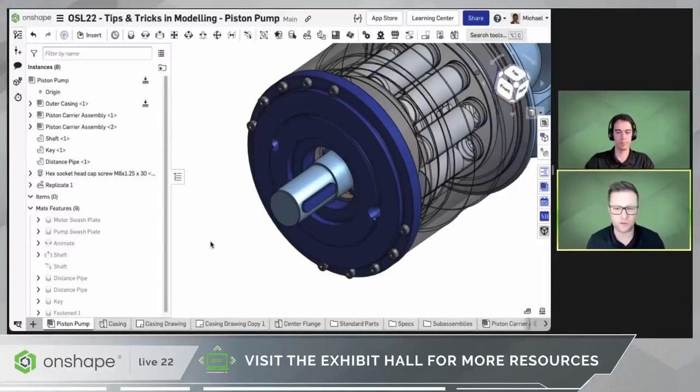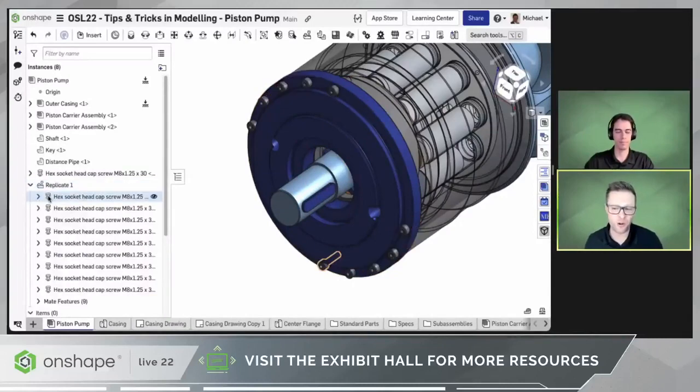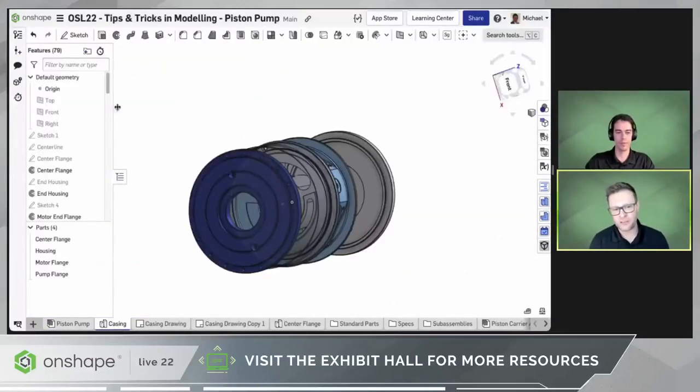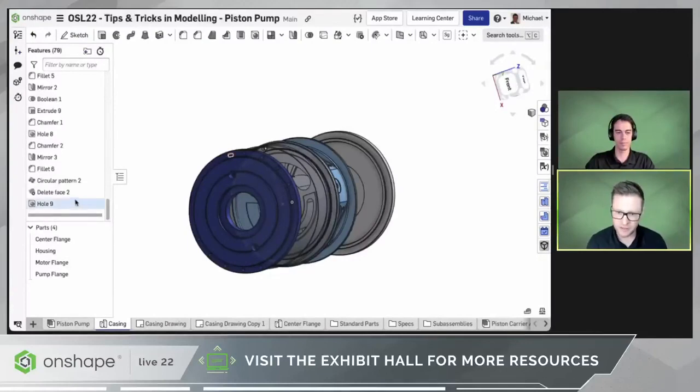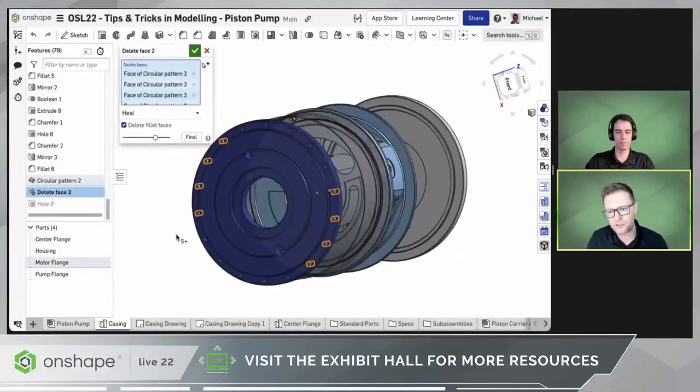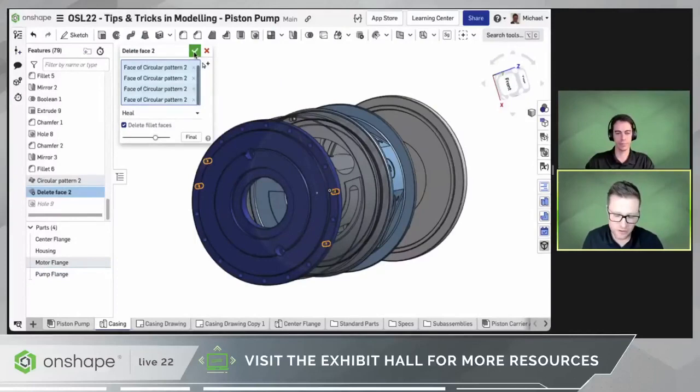This saves me from having to pattern or something like that. Because as soon as something is changed in the hole pattern, for example, irregularities are brought into the hole pattern, a simple part pattern really reaches its limits. For example, here in the part studio, let's jump back to the part studio, I retrieved some previously deleted holes to create an irregular pattern. So I just delete some holes to demo how it works.